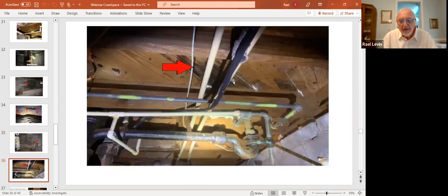Rot underneath the floor, we're going to see that, so that's why we want to get up underneath the bathrooms. It could be something simple like there's caulking missing on the side of the tub. And because of that, water's coming down and rotting out some of the floor right there. It just depends on where we are and how we can report.